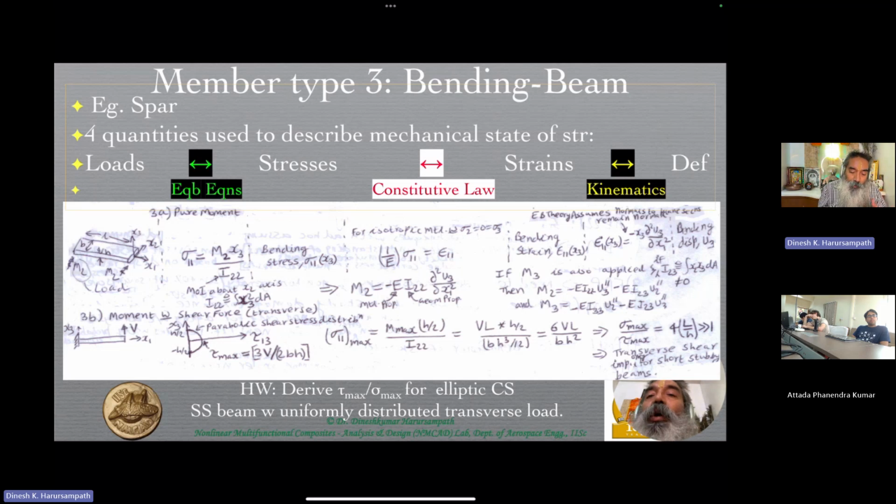Remember, when we were talking about thin shells, we were talking primarily about the major loads, major stresses, which are the bending stresses, torsional stresses, etc., which are better if the material is spread outside. Whereas here, you are saying that it is better if you have the material inside. But since this is a much smaller stress to deal with, it can be dealt with by materials as flimsy as a foam in a sandwich, or a honeycomb made out of aluminium thin plates, again, in a sandwich kind of construction.